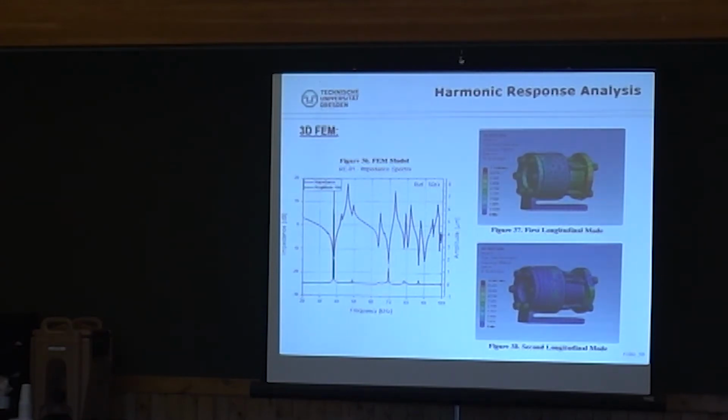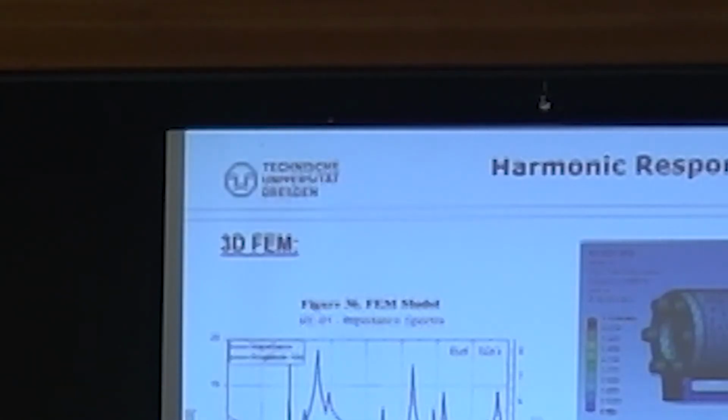I have looked at that, and they are higher frequencies. So why would that be relevant to something that is operating at 35 to 40 kilohertz? Reflections? Yes. You have standing waves. Extremely small amplitudes. If you have a quarter wave difference between reflecting surfaces, you have an infinite impedance. Of something that has extremely small amplitude by orders of magnitude. Doesn't matter.